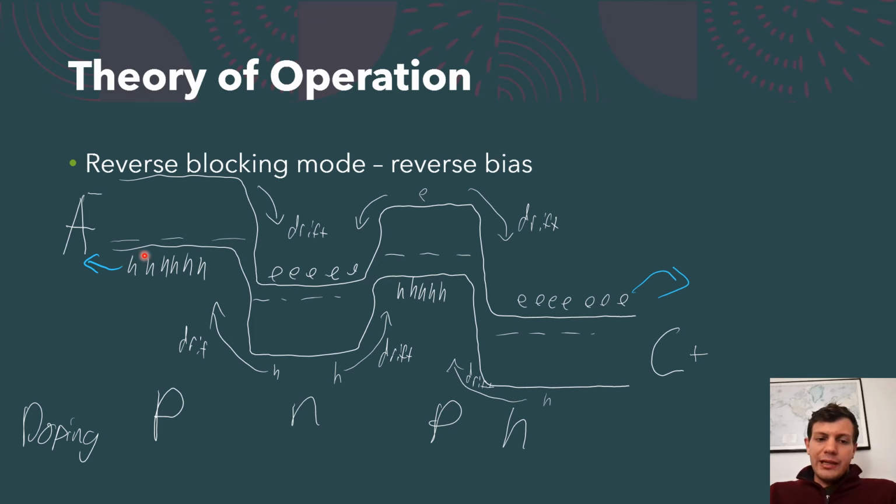So holes are being drained from the device at the quote unquote anode. I'm just calling it that so we can keep track of which side of the device is which. But holes are going to be drained. Since these gates were floating, we're going to see lots of drift current as the potential shoots down to meet, so the Fermi levels will realign up here. In reality, this will happen pretty quick, especially as the current just falls out.